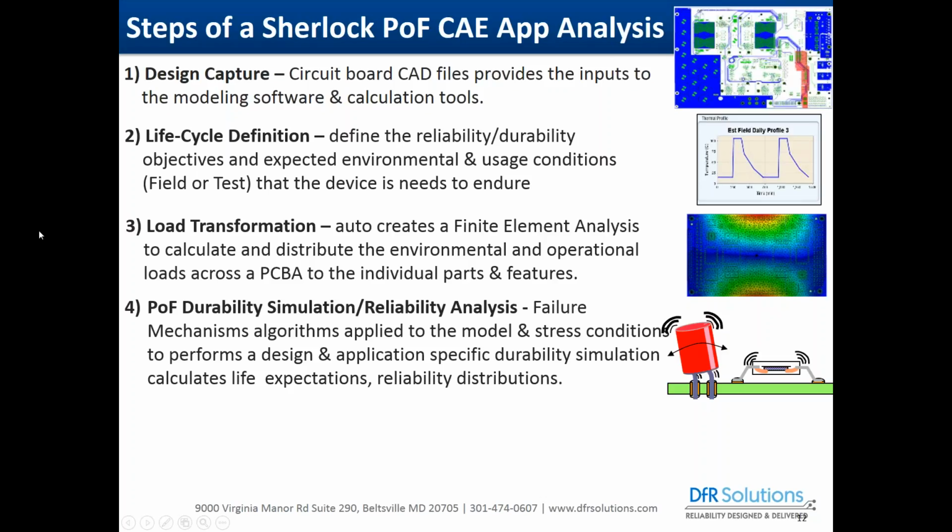Then we feed the component information and the stress information that it is enduring into the physics of failure durability simulation models, the failure mechanism models. And this is where it comes up and says, this part enduring this kind of stress profile for this long is going to degrade to this point.